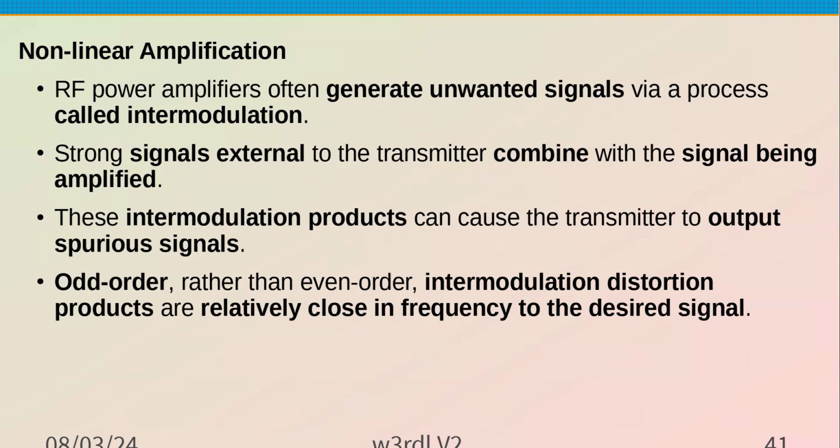In an amplifier that's non-linear, you get some of that mixing effect with multiple signal frequencies, and you get intermodulation, which are those sum and difference frequencies.